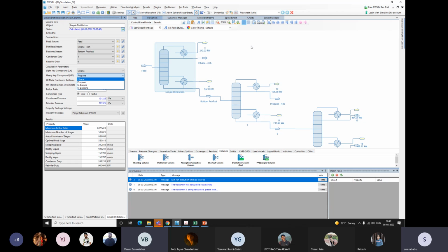We have to do both, and we have to see how much net amount of energy, like we have the reboiler duty. So this is positive. We are removing the energy, and here we are supplying energy, and we have to calculate the net energy demand and the number of critical stages, and how they come out. We have to do it. There is no simple straight rule that gives you this.